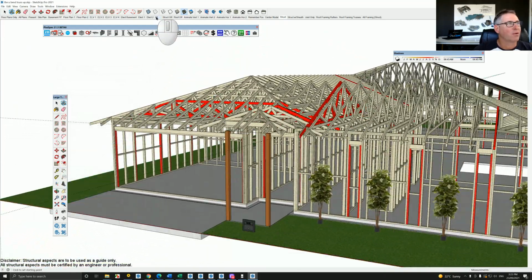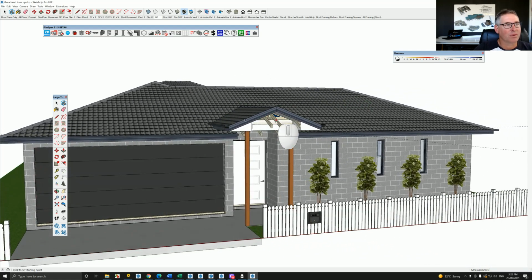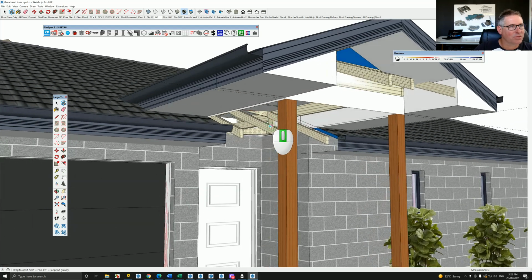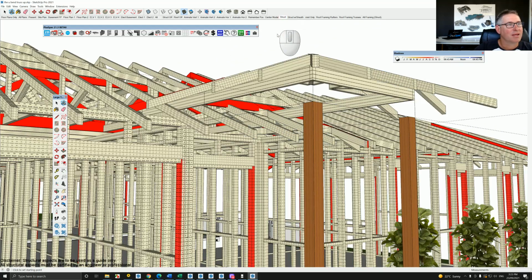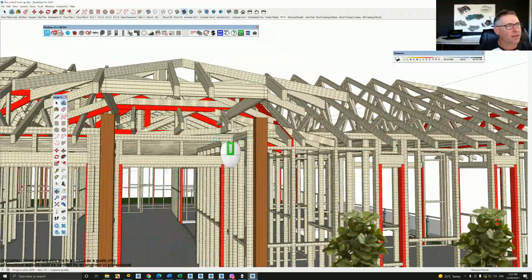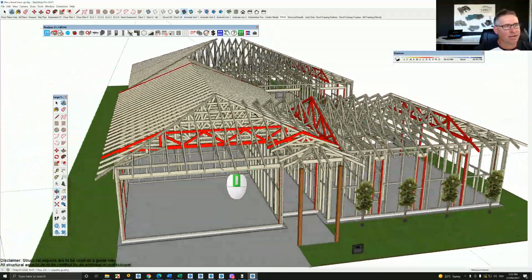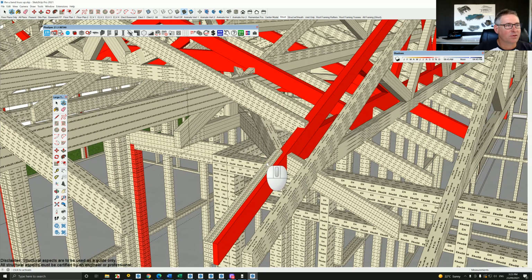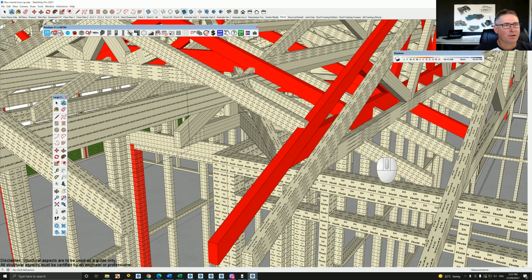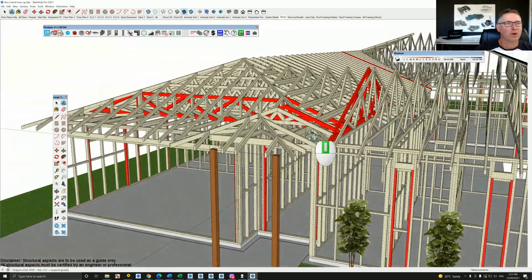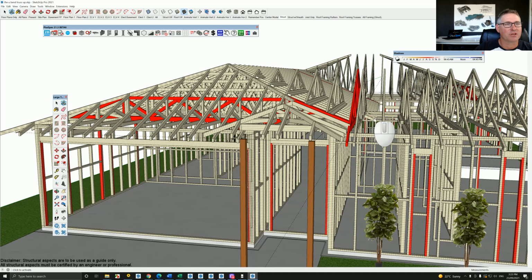If I go back and look at all, my roof is the way that I want it to be as well. However, I should have drawn this as a gable. And you'll also notice that we have these tails coming through the roof, which, if we go to the structure, are the overhangs of the truss. Now we don't want them in there, so if we click on the on-click function here and get rid of those, and there will also be some where any other girder was. You can see them here. Okay, get rid of that one there. The girder is the defining factor, nothing would run through it, usually. Get rid of those, click them there, and you can see it won't be long before I've tidied that model up and have it ready for construction.